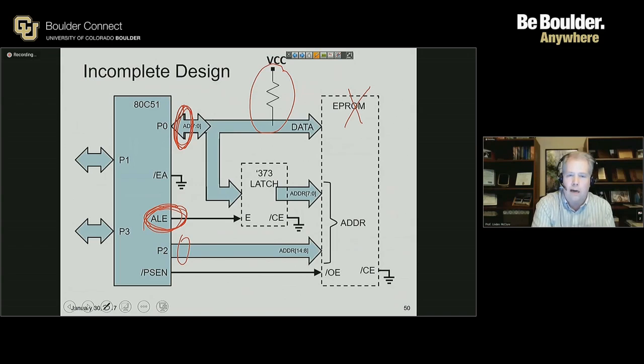You have to tune it now because that problem could keep coming back to you as you go through the semester. So each time you change your processor or you change your clock source, you need to tune that so that it always comes up at power on at the right frequency. Once you've tuned it for power on reset, you also need to test it for momentary reset or runtime reset. So you keep putting in a reset, letting it come out of reset, and verifying ALE always comes up at the right frequency. If it ever comes up at the wrong frequency, you need to keep tuning it until it comes up right.